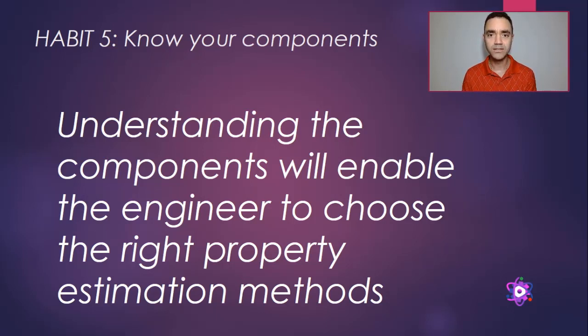And knowing your components is very important, because the fluid package is what adds all the thermodynamics results to your process simulation. So if I'm doing a steam generation process simulation and I use Peng-Robinson, I will find some results, but that will not be as accurate as if I use the ASME steam for the process simulation.